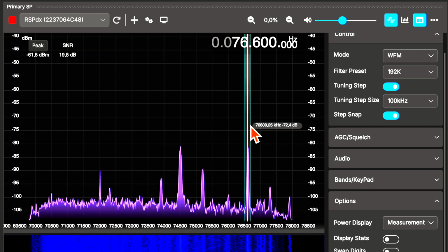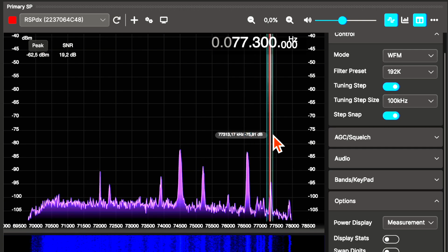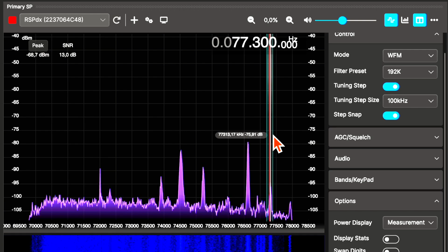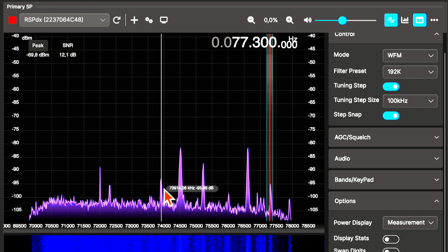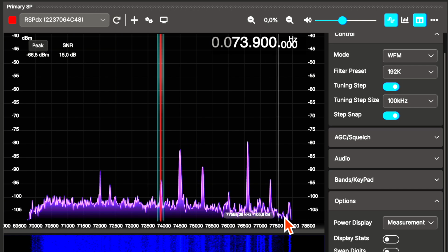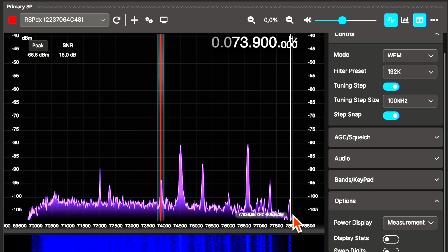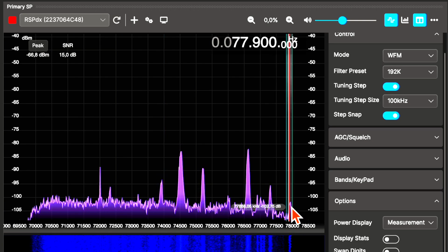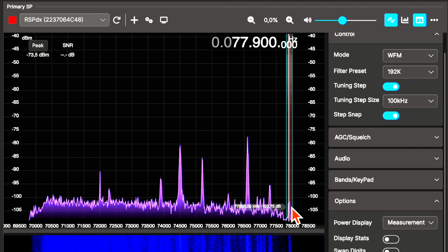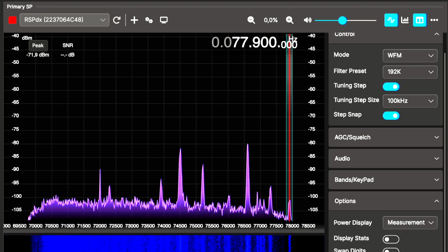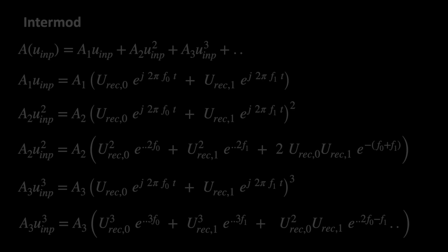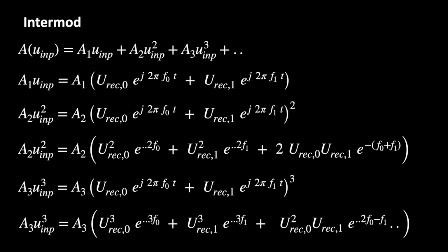We can hear a mixed audio signal from 2 or more stations at the same time, and I can even identify which ones they are. This way, we can actually find the FM stations from which the intermods are caused. Considering the RF signals are mixed including modulation, it is surprising that we can identify an audio signal at all. Why is that? Signals are retaining their modulation, including phase relations, when mixed.